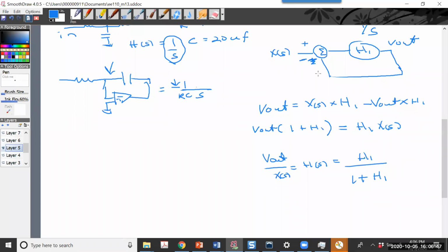Notice how we're subtracting the output. That's negative feedback, right? But notice how it's positive in the transfer equation. Well, that's because when it's subtracted here and you bring everything onto the left-hand side, it turns positive, right? So yeah, the negative feedback actually has positive coefficients in this equation. All right.